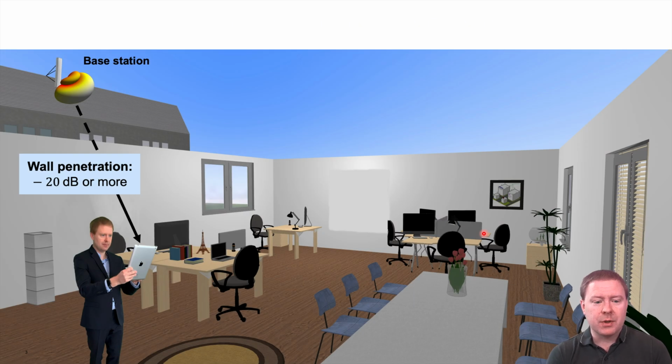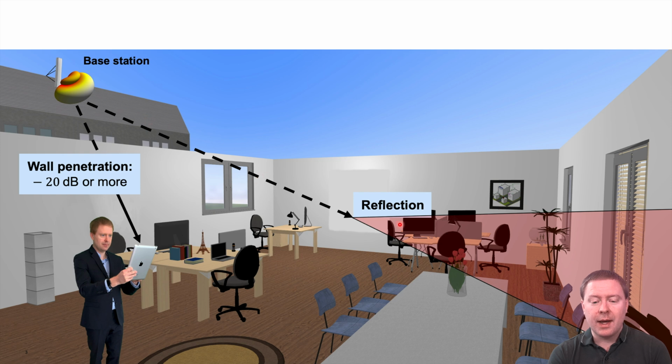So the idea might, for example, be here I'm standing in my virtual office, there is a base station sending a signal, and the signal would have to go through the wall, and when it does that, you lose 20 dB, which means that 1% of the power that hits the wall actually goes through it. So that is a large loss in power. In this scenario, the signal might go through the window and hit this area over here, but probably it will be reflected towards the far end of the room due to the geometry of wave propagation. So what can we do about that?